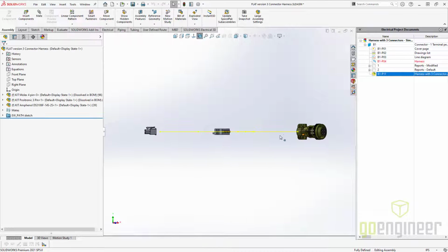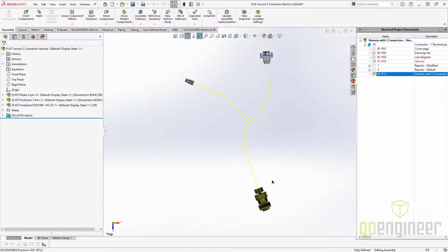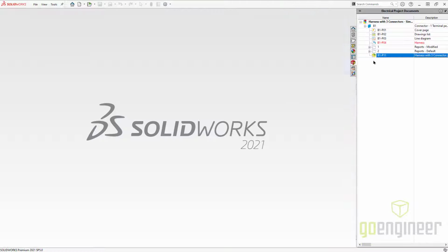So it's kind of the same assembly, you'd have to go through and do the association, but even though this is a 3D sketch for the wire path, all of my parts are planar. And the idea behind that is I could wire it up as if it was going to be on a drawing or on a pin board. And then I don't do the flatten route, and I could add other things to the route subassembly. So I could add zip ties, back shells, clips, all that type of stuff. So, all right, let's get back to the assembly that I did have open.